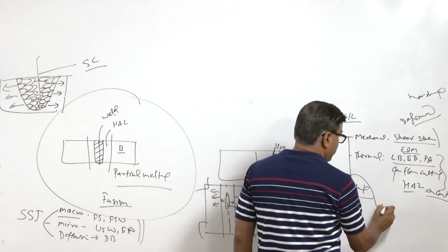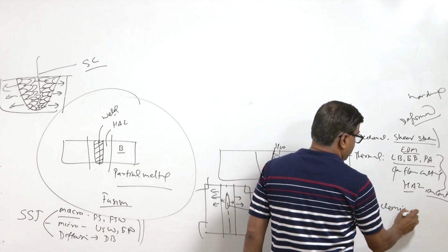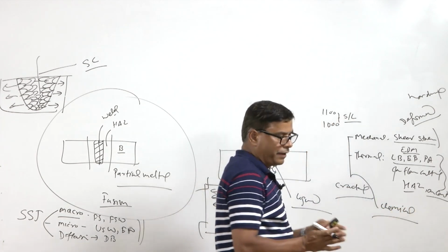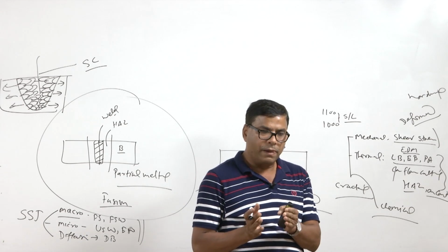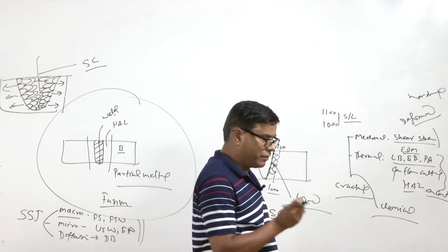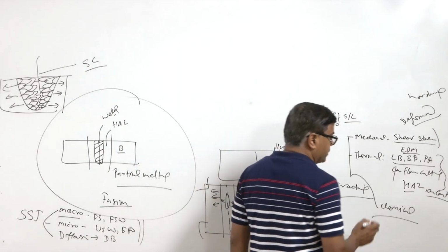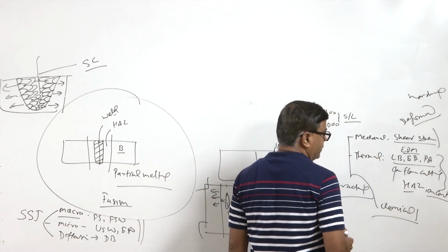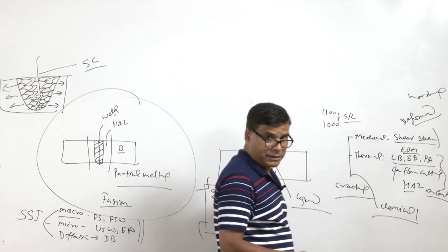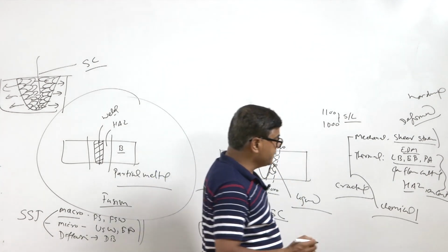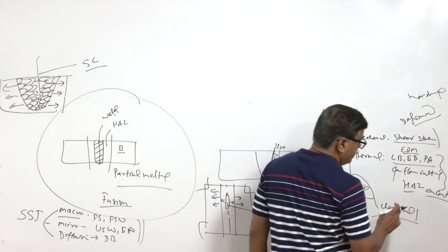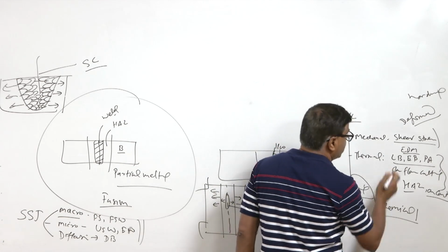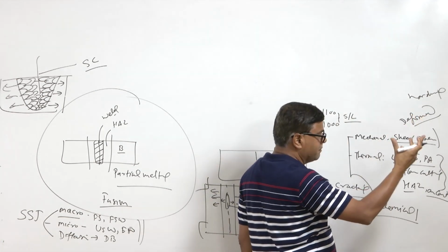Then there is a chemical based approach, where controlled chemical interaction between the base metal and chemicals is used for controlled dissolution of the metals, so that the material can be removed in a controlled way in order to have the desired size and shape. In this case, especially whenever material is removed by chemical methods, there is no deformed layer like in conventional machining.